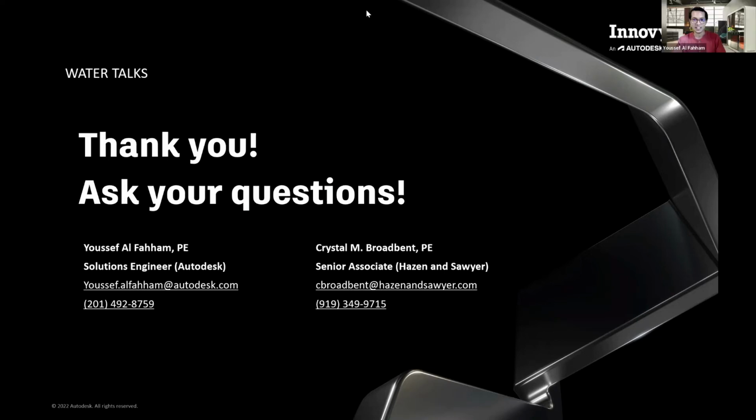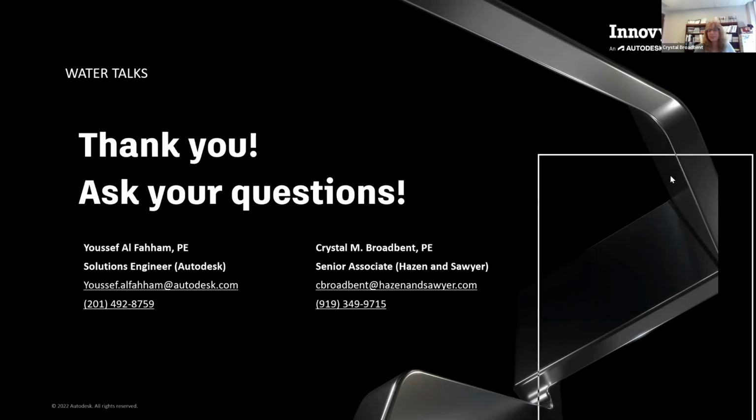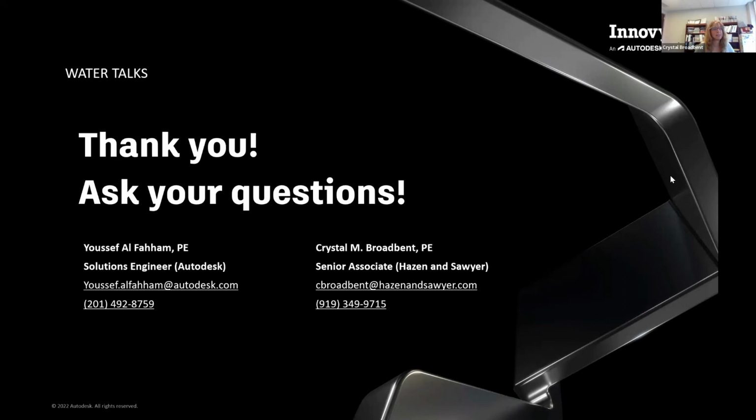Yes. Can the surge start time be set to automatically do surge analysis when the pump shuts down? No, you'd have to run the EPS to find out when the pump is going to shut down and choose that time to start your analysis. It doesn't automatically choose that. You do have to pick a time to do that.